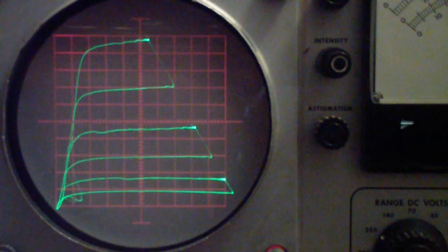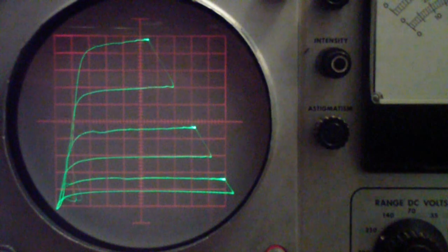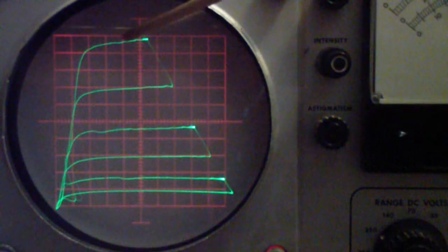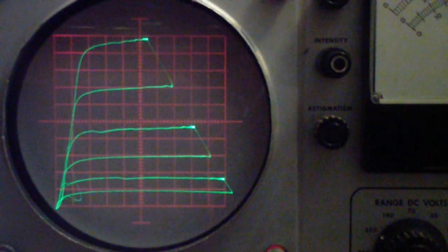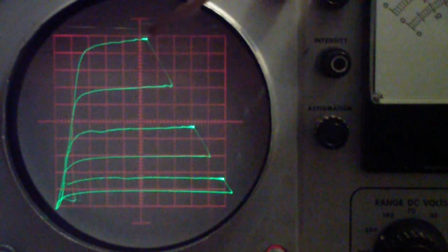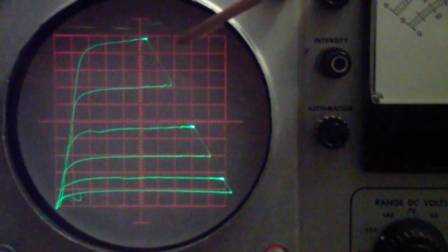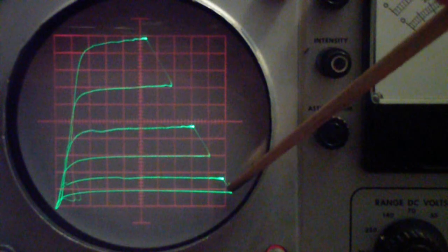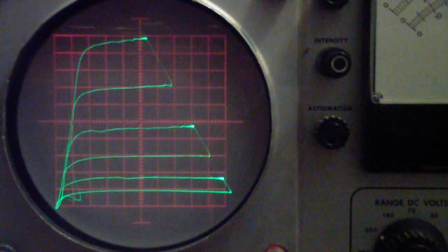And the series resistor is there for a couple of things. One is to develop the voltage, and the second is to develop the voltage difference as the signal changes. In other words, it is the plate load resistor. But the reason the series resistor causes this line is that the slope of this line from here to there is simply the resistance.